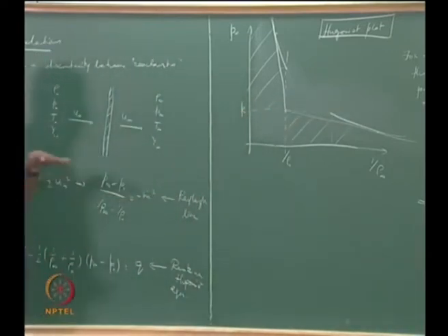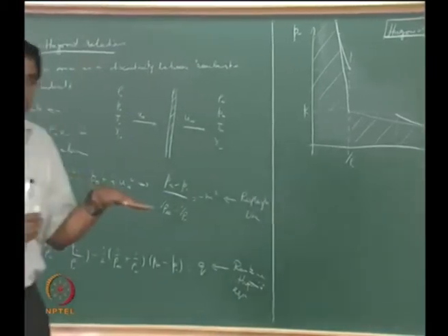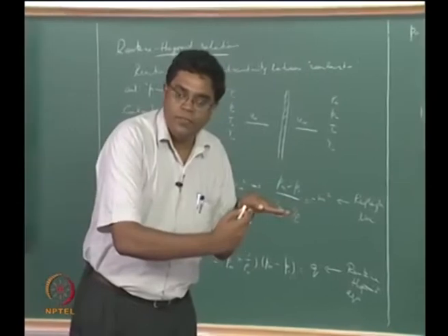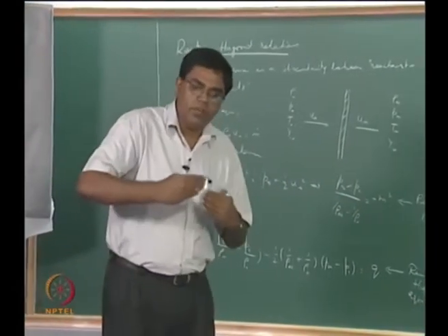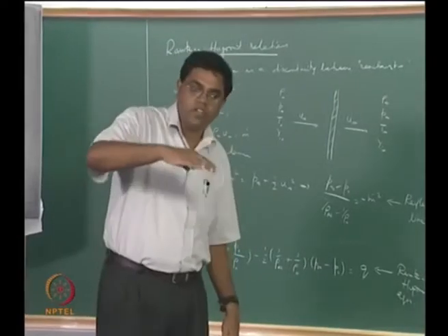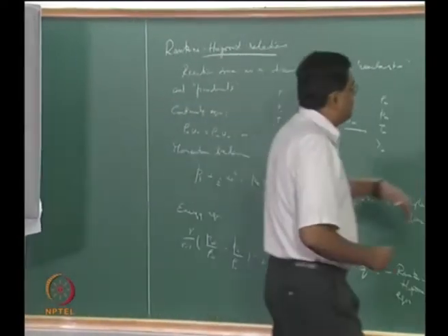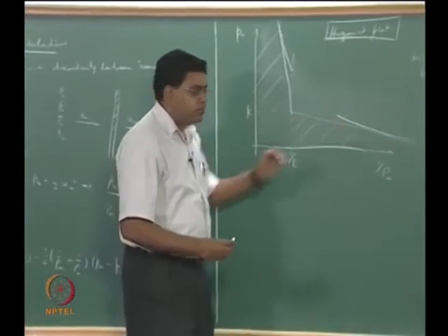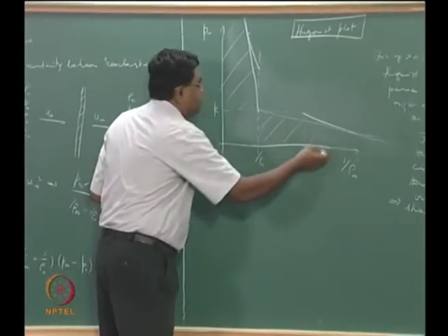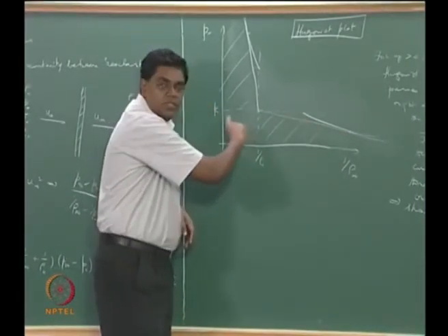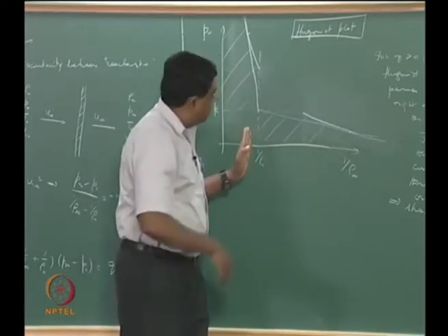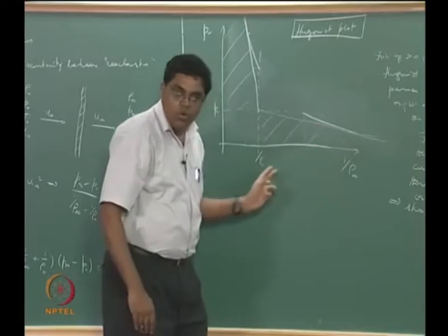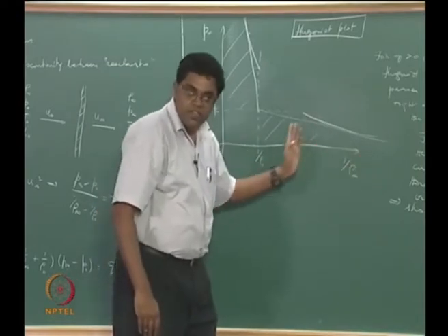So in the one extreme you started out with an isobaric process corresponding to very slow waves, right, and then you could think about a little bit faster waves but with a certain decrease in pressure, not a whole lot of decrease, okay, but from here to here you see that the pressure is decreasing only a little bit, okay, but the expansion, that is the density decrease as you go this way, 1 over density increases, so density actually decreases.